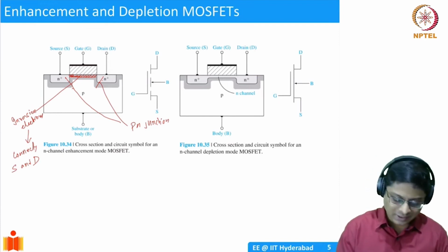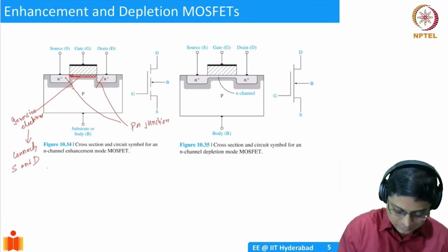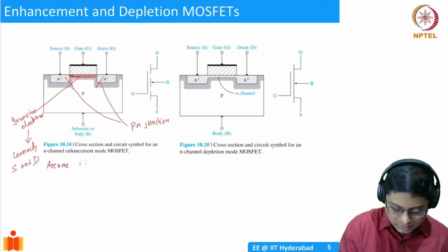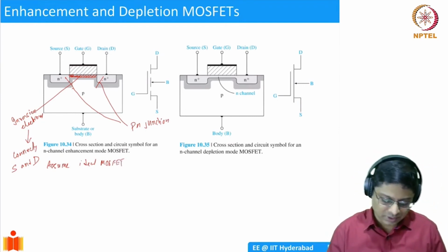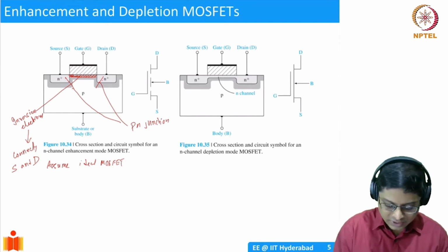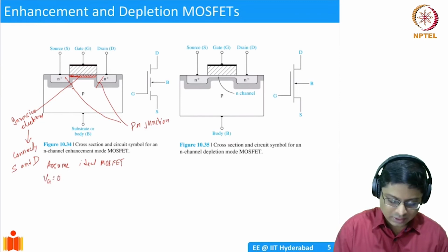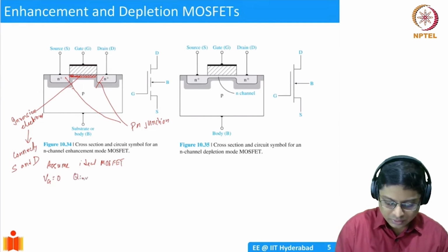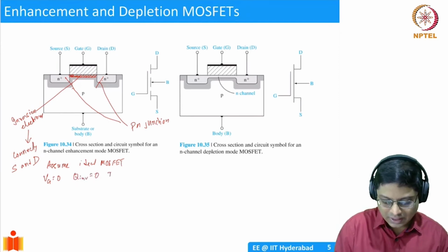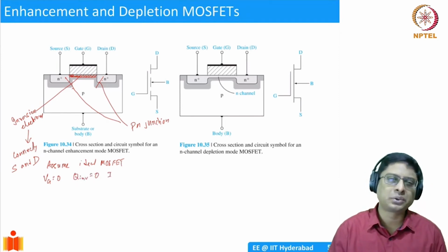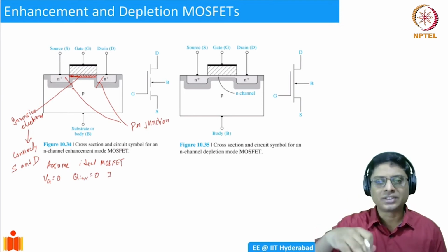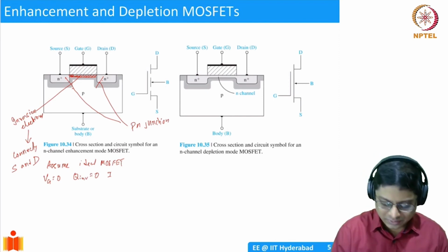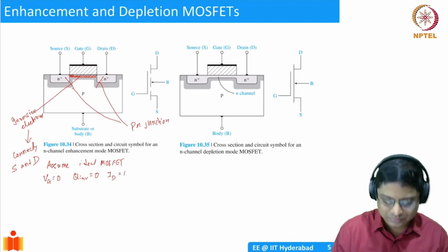Okay. Let's assume an ideal MOSFET. I mean, basically an ideal MOS cap, and then there is the FET structure. When you have such a scenario, if your VG is equal to 0, I'll say Q inversion equals 0. That means we could talk of drain current or source current. Both will be equal here because the oxide is perfect, right? There is no leakage. So typically the source and drain currents are equal. So I'll simply talk of drain current equal to 0.